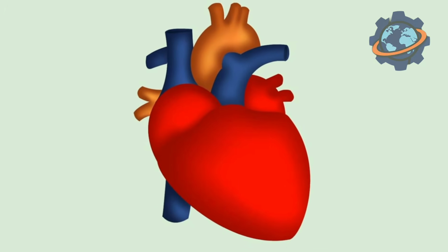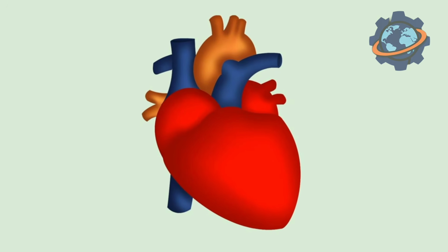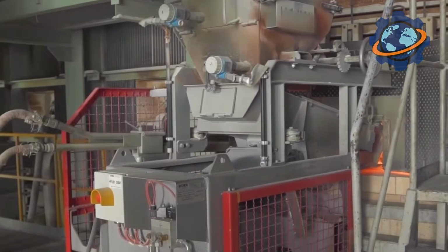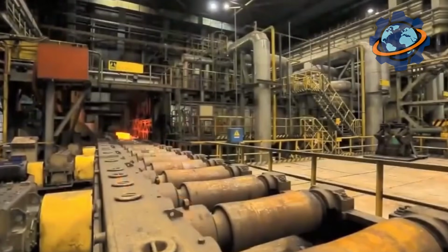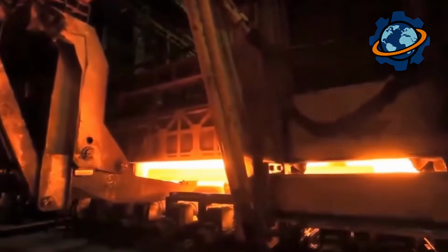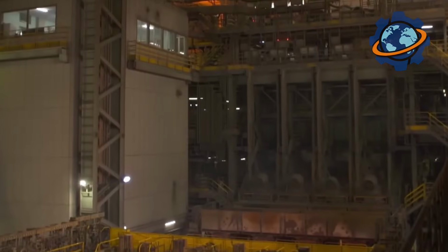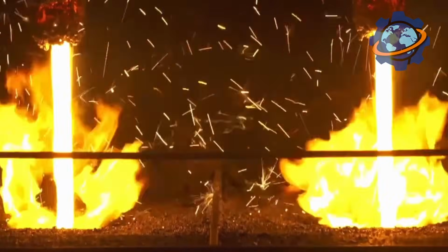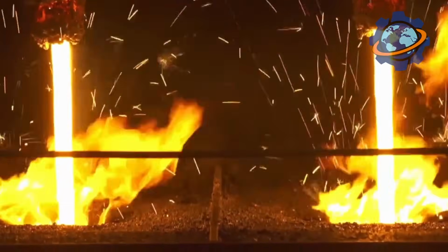This is the heart of the whole process. Imagine a thick steel plate with a perfectly round polished hole, the diameter of which exactly matches the diameter of the future rod. The die is heated to a certain temperature. When the wet strand is pulled into this hole, several things happen at once. First, the die, like a press, squeezes out all the excess resin, leaving only the necessary amount.